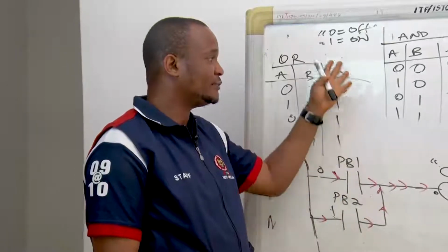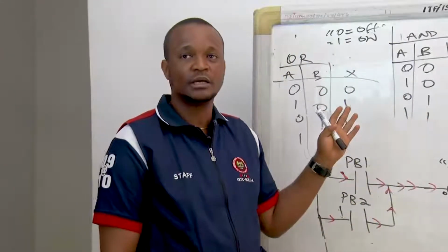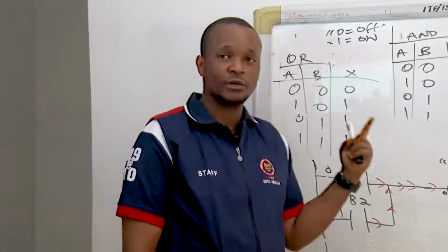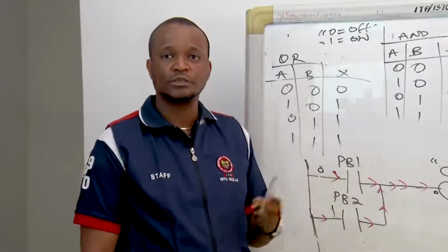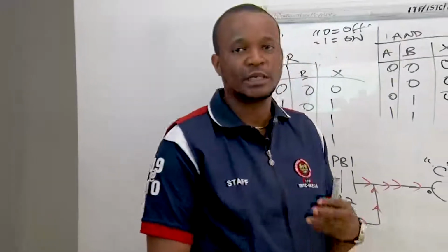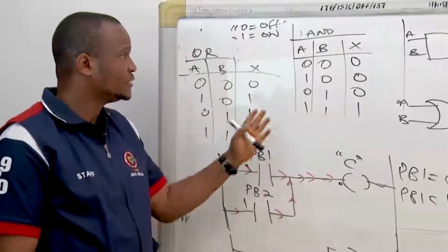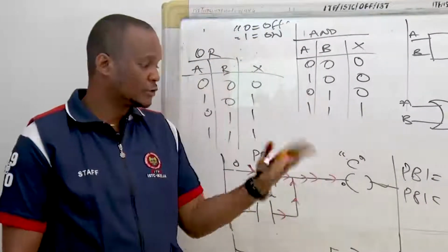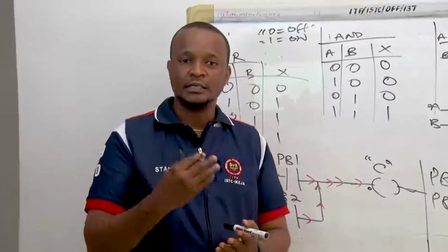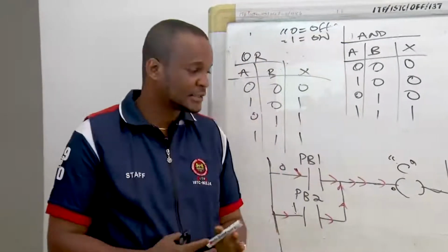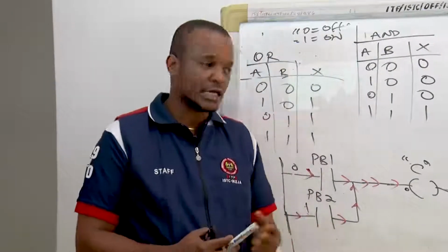So we have said that we have 5 standard PLC programming languages: the sequential function charts, the instruction list, the function block diagram, the ladder logic, and the structured text. Out of those 5, the most popular one is the ladder logic. We just showed you how the ladder logic looks. It has a power rail, it has a rung, and then it has some contacts, which we call examine if open or examine if closed, and then we have the coil and how they are arranged.